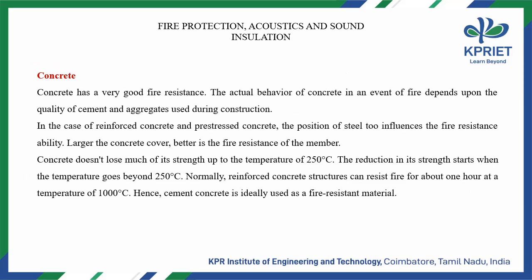Concrete. Concrete has a very good fire resistance. The actual behavior of concrete in an event of fire depends upon the quality of cement and aggregates used during construction. In the case of reinforced concrete and prestressed concrete, the position of steel too influences the fire resistance ability. Larger the concrete cover, better is the fire resistance of the member.